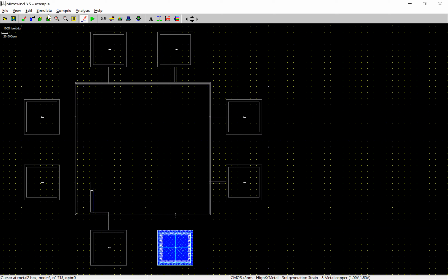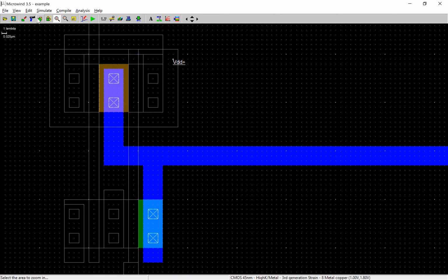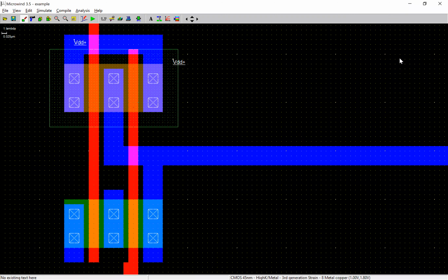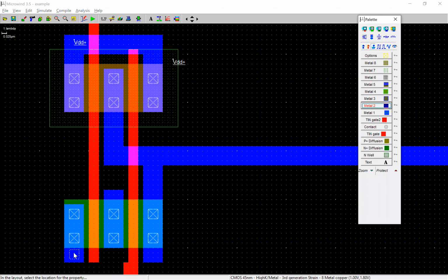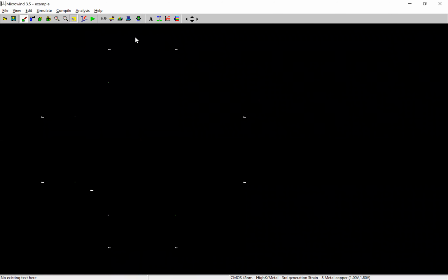So ideally, it's the same way I can connect the VDD supply, okay? But let's say I just go back, zoom the NAND gate, and I just apply the VDD and supply here just to be quick. So I take a VDD supply from here. Otherwise, it should have been from the pad. Because what happens when you draw a track till the pad, the RC values of the wire paths also accumulate on your loads. So that has to be checked and challenged, okay, that they are working properly or not.